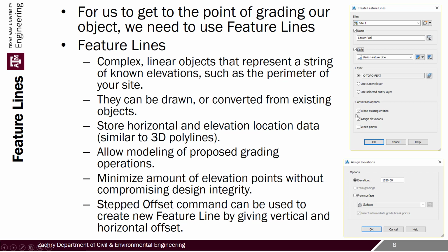Sometimes I know a lot of guys that will uncheck this box. They'll make sure they have their polylines in their original design in a certain layer that they can control by turning on and off, but they don't want to lose it when they're using those lines for feature lines. And so they'll uncheck this box. It's going to be up to you to develop your workflow and whether you want to use those again. I tend to like to use them again, so I tend to uncheck that box. But what we're going to be doing today is not really going to make a big difference.